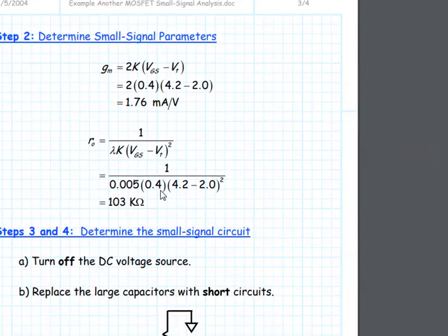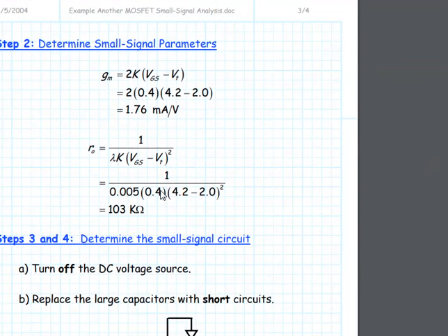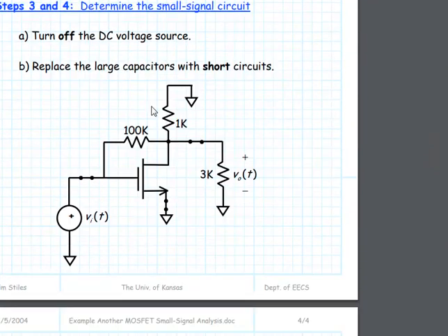So then I want you to continue this problem. I just show you the shape in the AC mode now. Look here what I have done. I have replaced the capacitors with short circuit now, right? And I have eliminated the DC sources. So the circuit is gonna look like this.